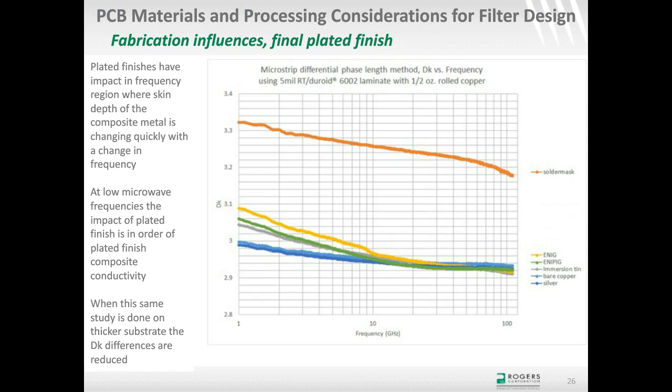So this is one of those topics that I don't run into very often. And usually at higher frequency, it doesn't matter that much, as you can see here. But at lower frequencies, 1 gigahertz up to around 5 or 6 or 8, then that can matter. It can make a difference on the phase angle, these different plated finishes.